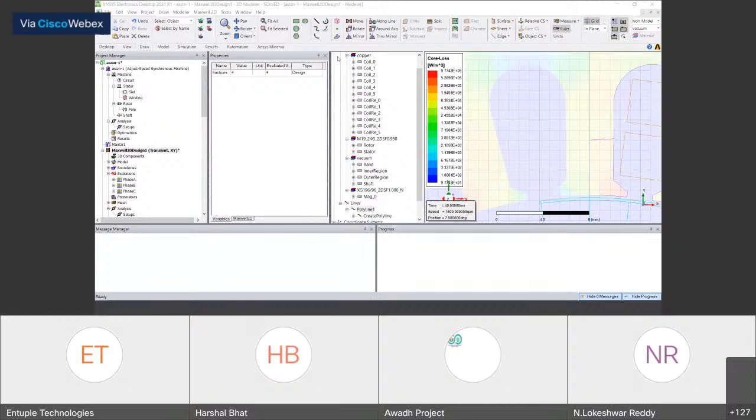So what a Hall sensor is basically, it detects a function of the flux and the direction of flux within your cross-sectional surface or cross-sectional volume. Okay, your sensor volume. So just like we plotted the flux on a line, you can get the flux inside a volume, and it will give you a good representation of a Hall sensor sensitivity.